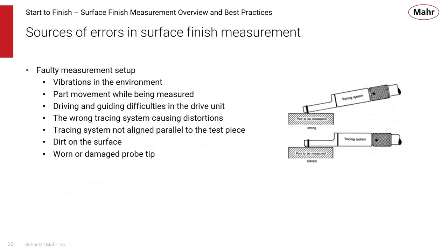In terms of the setup itself, vibration in the environment is going to cause readings or an influence on the results. If a part is moved during the process, that's going to cause an inconsistency within the results. Driving or guiding difficulty. If there's something going wrong with the drive, if it's getting stuck during its process or some grime might have got in there, that can affect the results. The wrong tracing system may cause some distortions in our process.